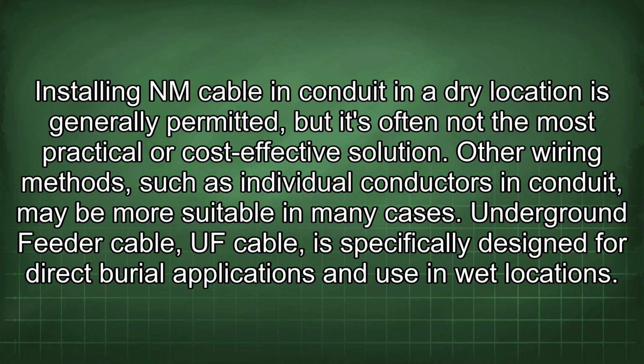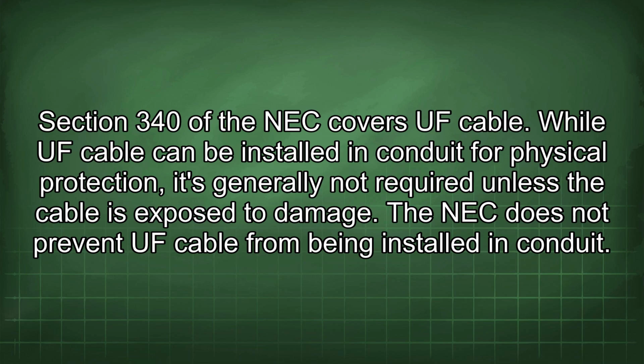Underground feeder cable, UF cable, is specifically designed for direct burial applications and use in wet locations. Section 340 of the NEC covers UF cable. While UF cable can be installed in conduit for physical protection, it's generally not required unless the cable is exposed to damage. The NEC does not prevent UF cable from being installed in conduit.